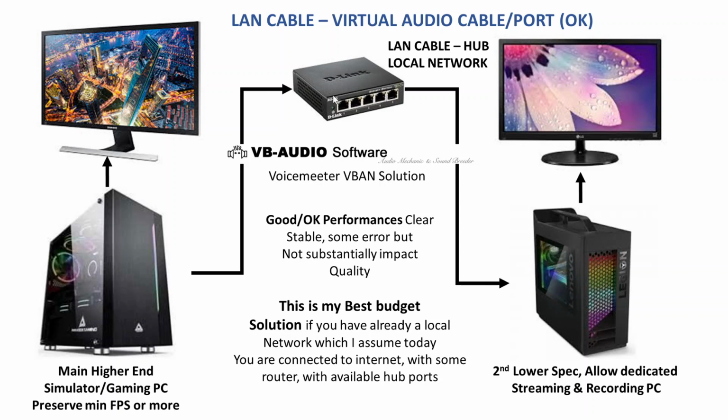You want to transmit audio from one PC to the other PC and remove the ground loops, because LAN cables use what we call twisted pair, so the ground doesn't matter. I forgot the term, but it's a balanced voltage kind of transmission, so it eliminates the noise effectively. So this is the best solution if you have LAN connections with cables and stable high speed.